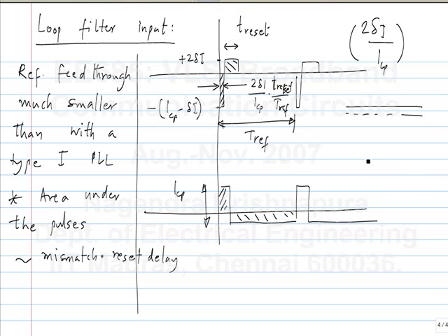Okay. But in addition to that, let's say you turn one switch on for some time, you will get a current pulse like this. From the other one, you may get something like this. Okay, there will be transient mismatch as well. So because of all that, there will be extra mismatch compared to the steady state mismatch. But even then, you can get it to be, let's say, around 10% or so. Okay. So that's the only thing that's there in the design of the charge pump, to make the 2 current sources match and switch fast.